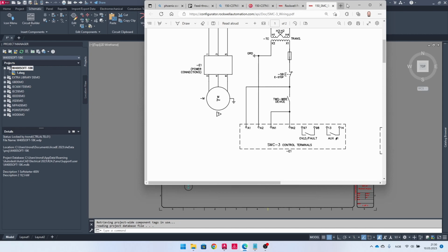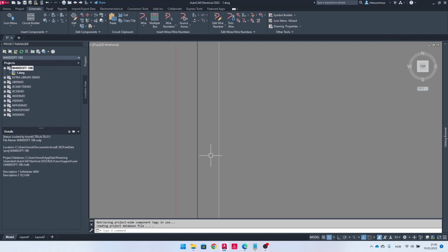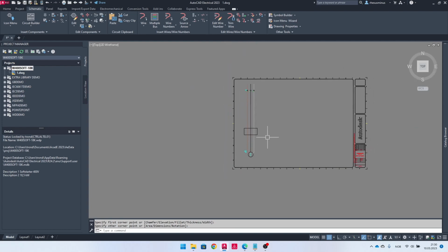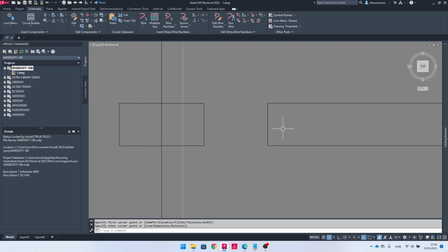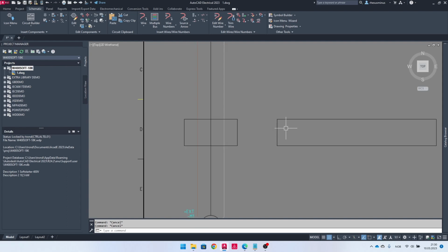So let's just create this as a custom symbol then. When I do my custom symbols, I usually start with drawing it in my schematic, so I can get a general sense of the size of the component. So I will have that one for the power connections, and then I will need some other symbol for the other connection points, A1, A2, and so on.